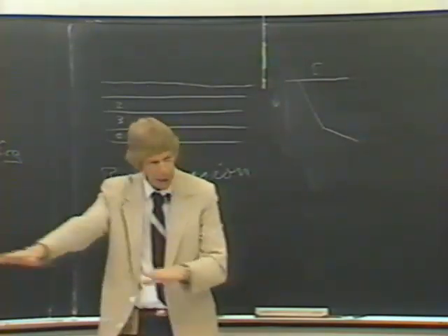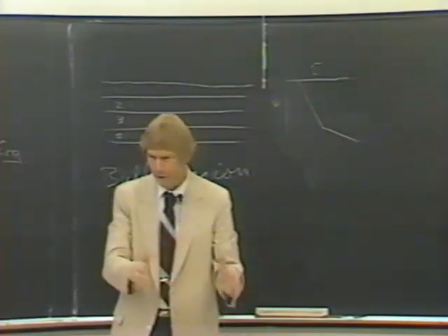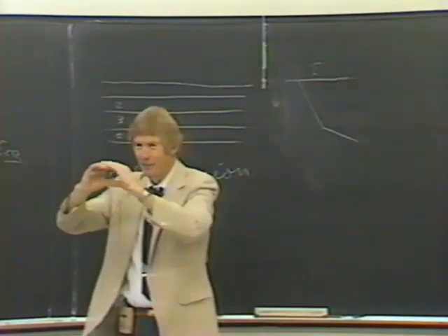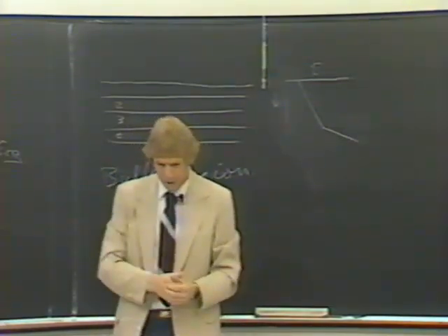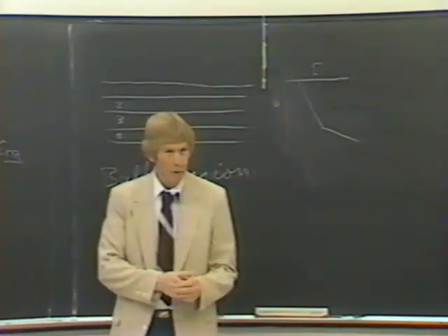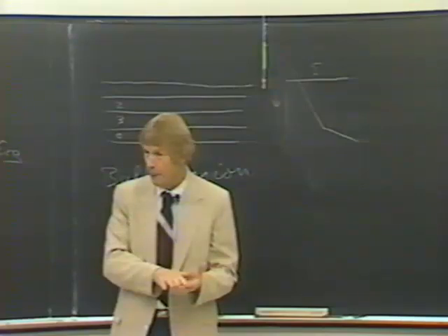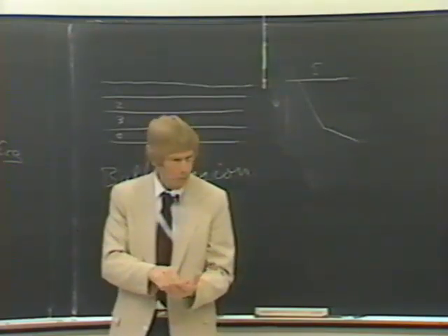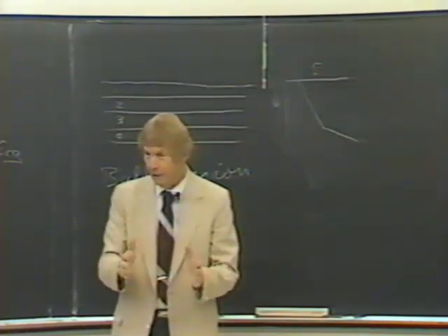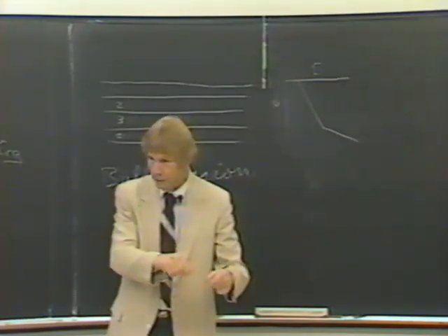first of all, made a bed of this cohesive material as undisturbed as we could. We took squares and put it in there, and put this caisson in it, and it was only about that big in this flume, and the flume was about that wide. And then turned the water on and let it erode, and we kept measuring the depth of erosion until it didn't erode any deeper. Then we modeled that with our numerical model. We modeled that system at that scale with the numerical model to give us some assurance that the model actually represented a physical system.